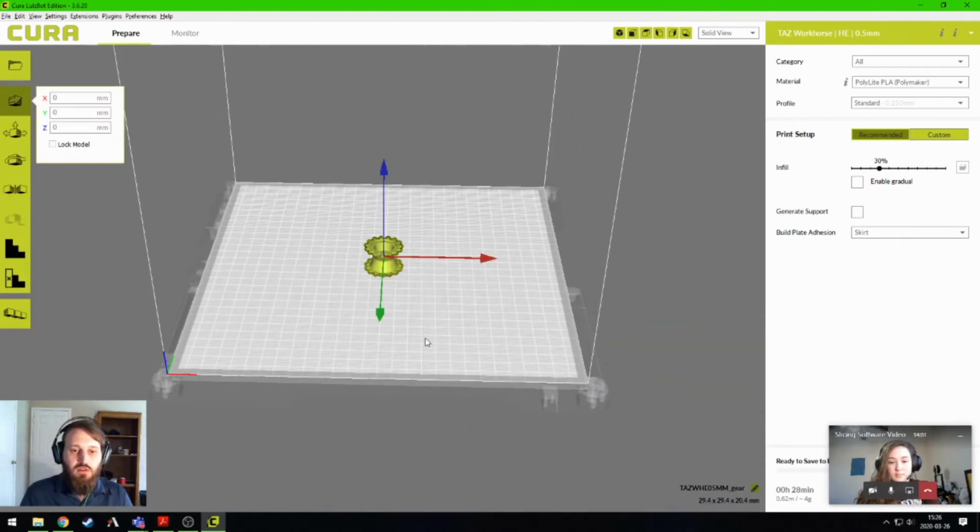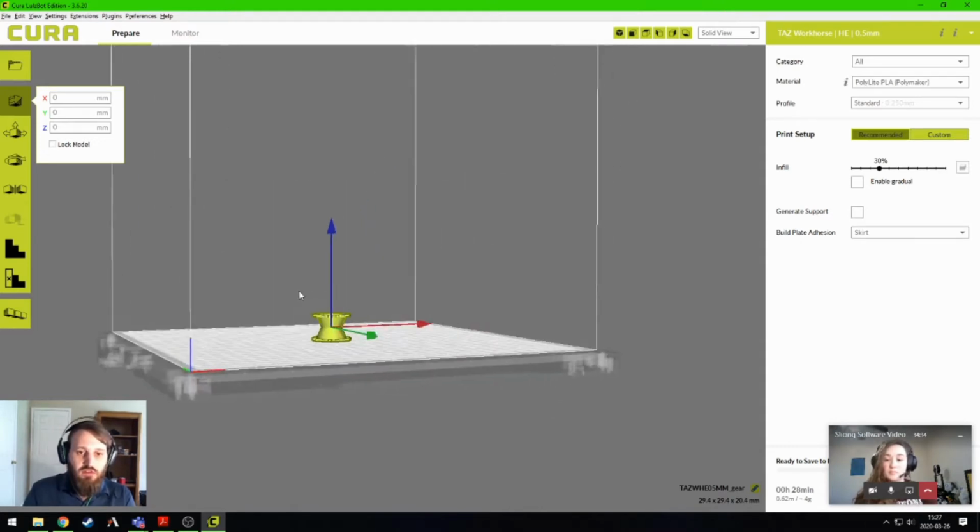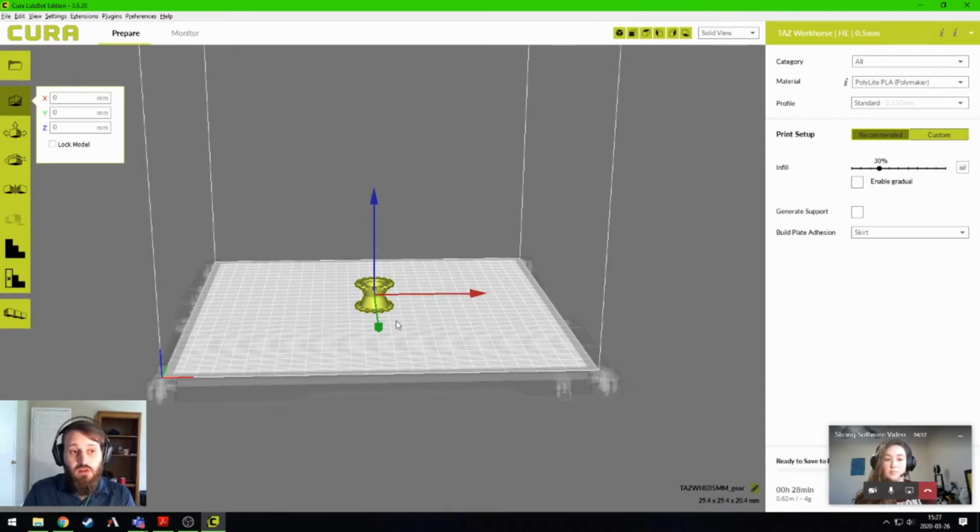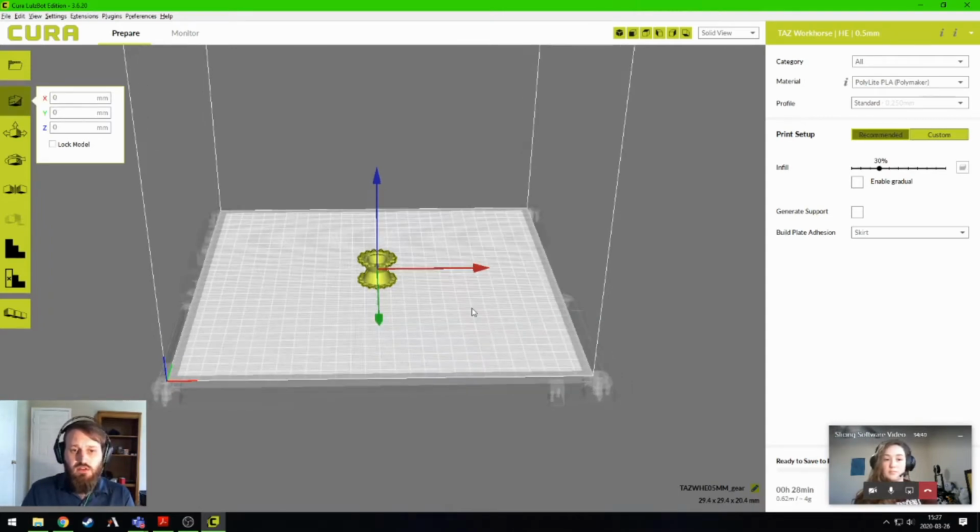So with this on the screen here, I can actually click on it and I can make a few other adjustments. Now this is not going to be for heavy modification. If you wanted to change the shape of that, we're not going to be sticking to the slicing software. We'd actually go into a CAD software, something that will allow us to edit and manipulate that object a little bit more, recreate the STL file, and then load it into this. This is more like I need to make a quick, simple size adjustment, maybe a rotation, maybe duplicate it or something like that, and then we'll make our adjustments over here for the print qualities in those different objects. So whenever we have it on the field here, we can do a few things. The first thing is position. So it usually centers it on the bed, right?